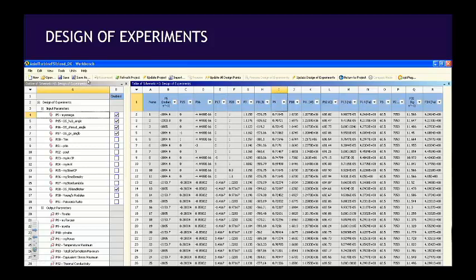So it's got DOE tools integrated into it. It depends on any inputs that you put in, and you can actually get some outputs from that. So you can have an output of a CL or CD. So what happens is that you make these changes, and the software runs through, makes the geometry changes in the background, runs through the simulation, outputs this file, and it goes to the next step. So you can have it all set up such that it's essentially scripted.